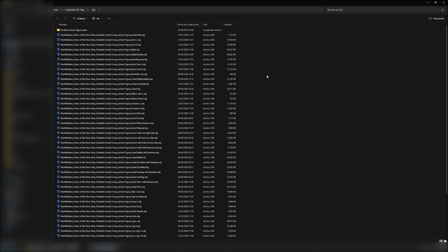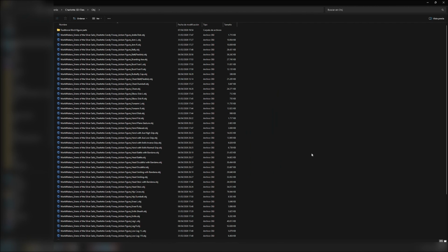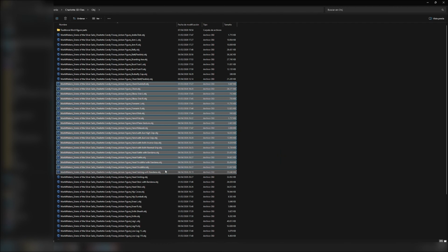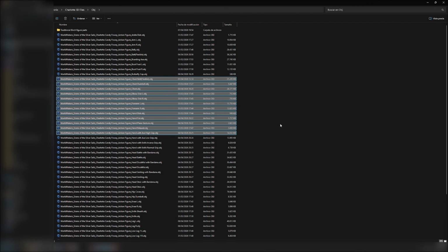If someone tells you, no, we only accept STL or FBX or you need those files, OBJ works exactly the same. In fact, OBJ, the only difference with STL is that it records a bit more information. STL, it's a great file type, but I just like OBJ.